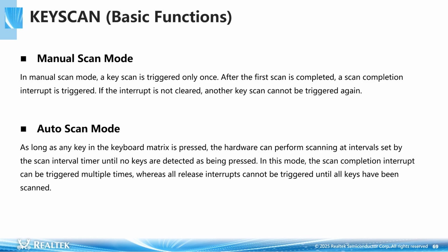In automatic scanning mode, after a key is pressed, scanning continues at set intervals until all keys are detected as released. An all-release interrupt is triggered. The scanning interval time, debounce time, and release time can all be configured during initialization.